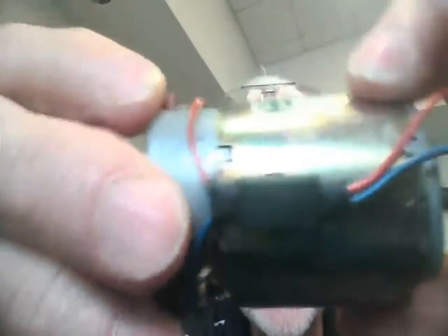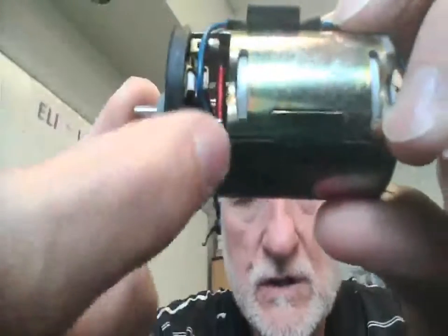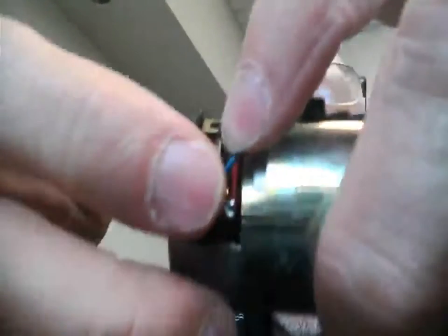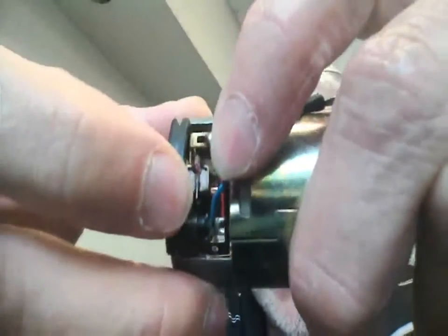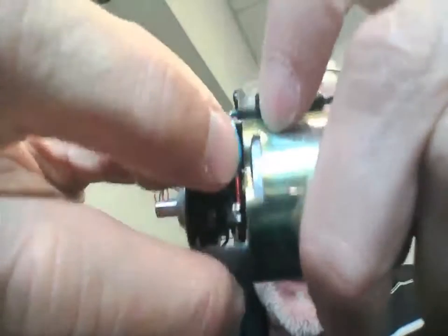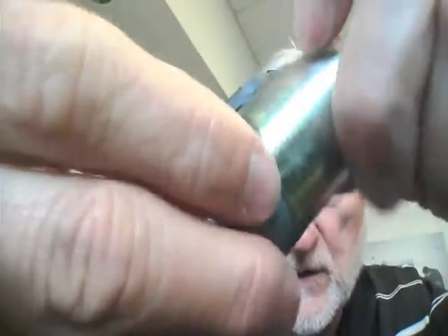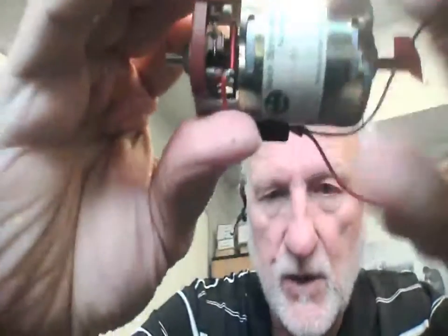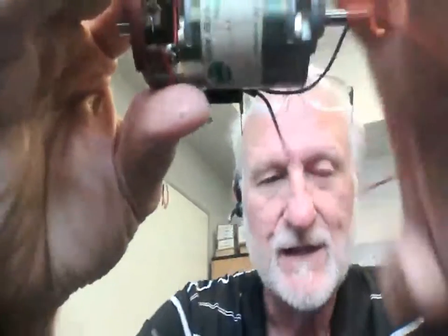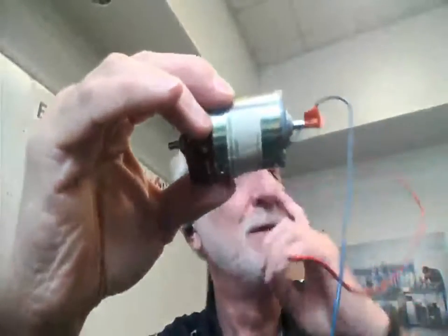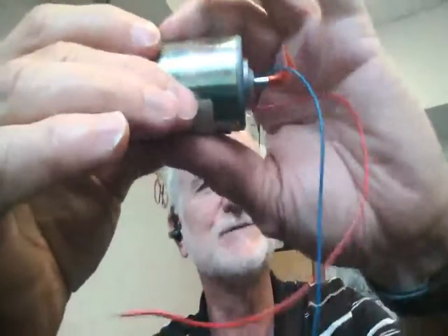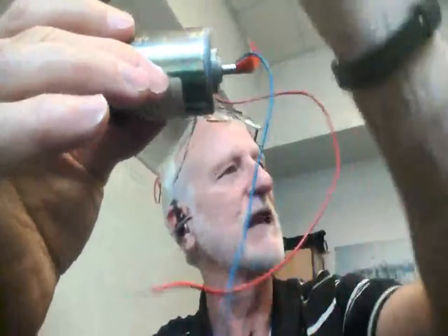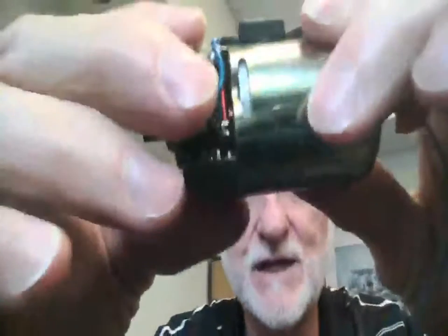So when we pass this around, I want you to look so you can actually see the brushes right here. So here's a little brush holder right there. Okay. And then you can see the wire connected to the brush holders. These little slots in here, by the way, these are what's holding the permanent magnets into place. You don't have to screw the things in because this is a ferrous metal, and basically they just clamp up there. Sometimes they glue them in.